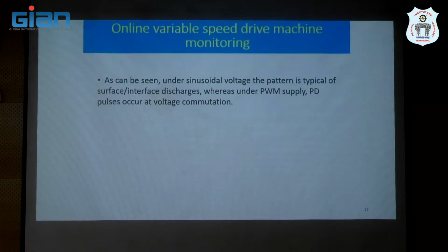These are the various types of discharges that usually occur. If discharges occur internally, they are internal discharges. If there are manufacturing defects, like voids and cavities, you have designed for a particular voltage level, but due to these switching aspects it cannot be withstood, and the cavity is an air medium compared to the other insulation medium. So the stress in the air medium becomes very high.